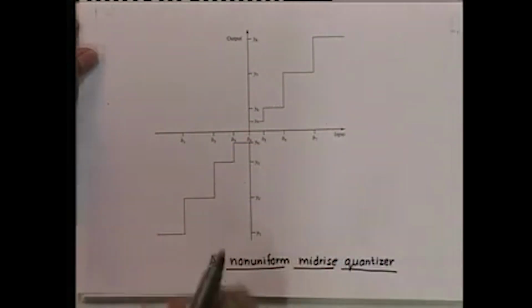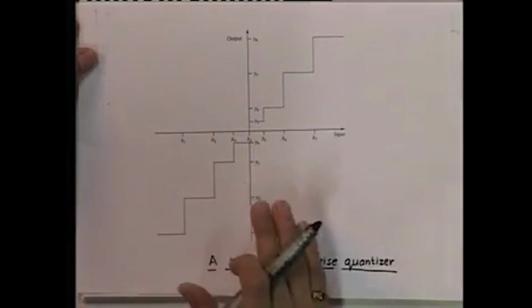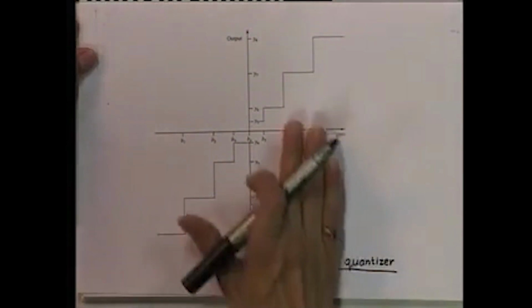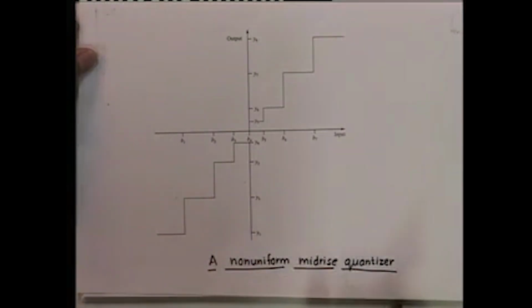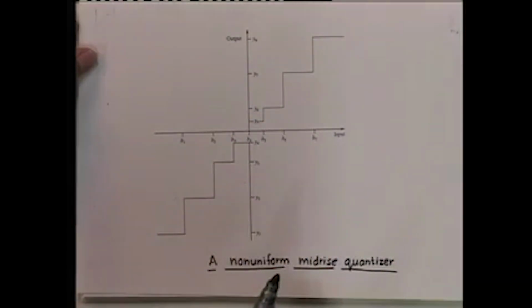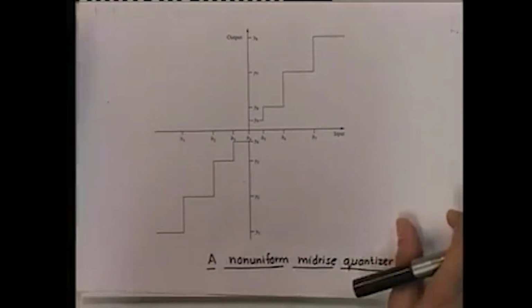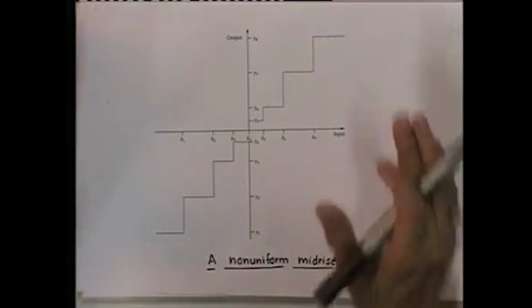a uniform quantizer. So, while a non-uniform quantizer provides lower average distortion, the design of a non-uniform quantizer is also somewhat more complex. The basic idea is quite straightforward: find the decision boundaries and reconstruction levels that minimize the mean squared quantization error.